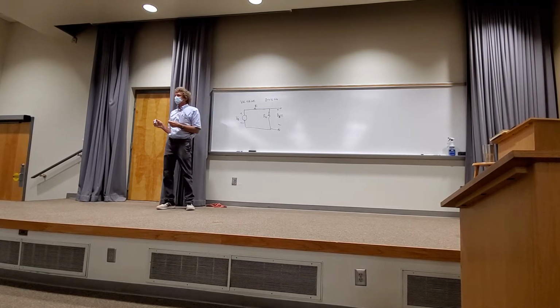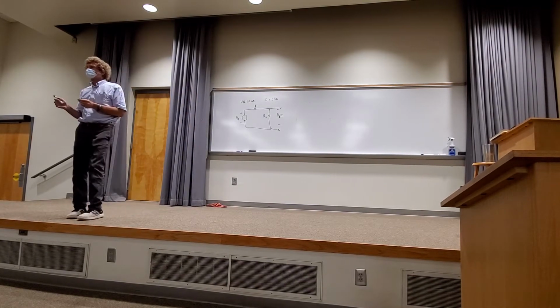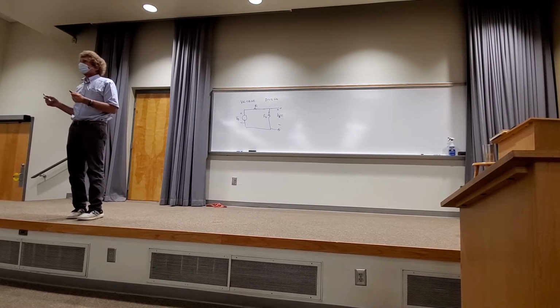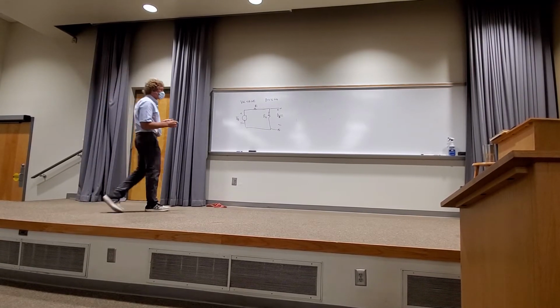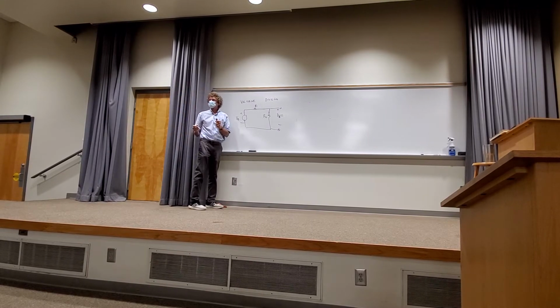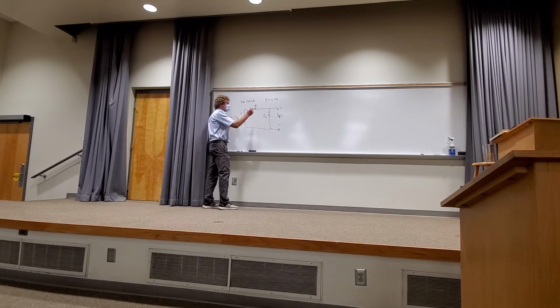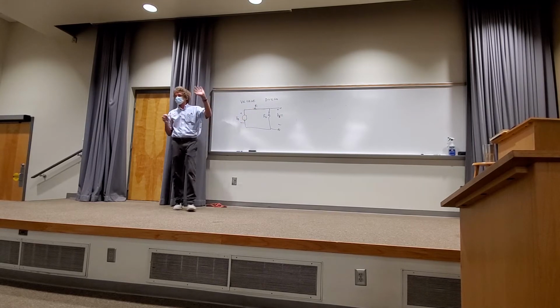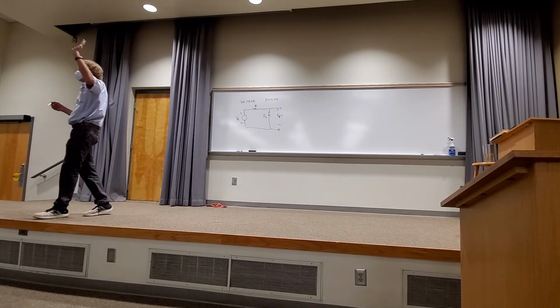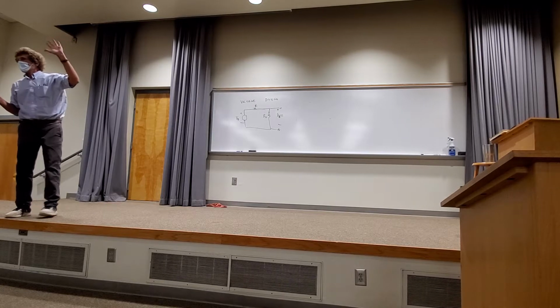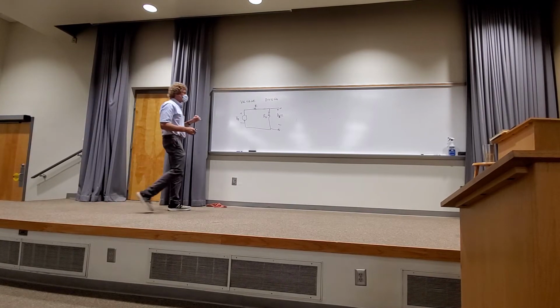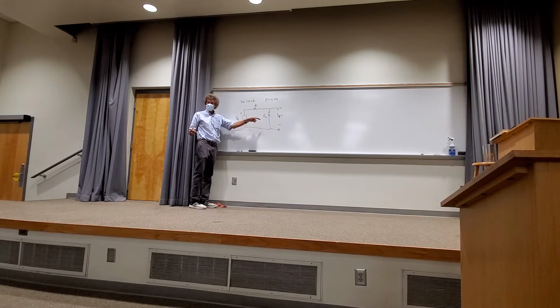So how do I get that voltage? Well, that's the question. Probably at least half of you, more like 2/3 of you, already kind of know just by looking how to do it. But some of you don't. So the first thing I'm going to say, if you ever are wondering where to start a problem, if you don't know how to get to the answer, start with what you know. You agree that these two resistors are in series. Series means they have to have the same current flowing through them, right? And if they are in series, can't we combine them down to just one resistance? It would be just a single resistance R1 plus R2. Do you agree with that?